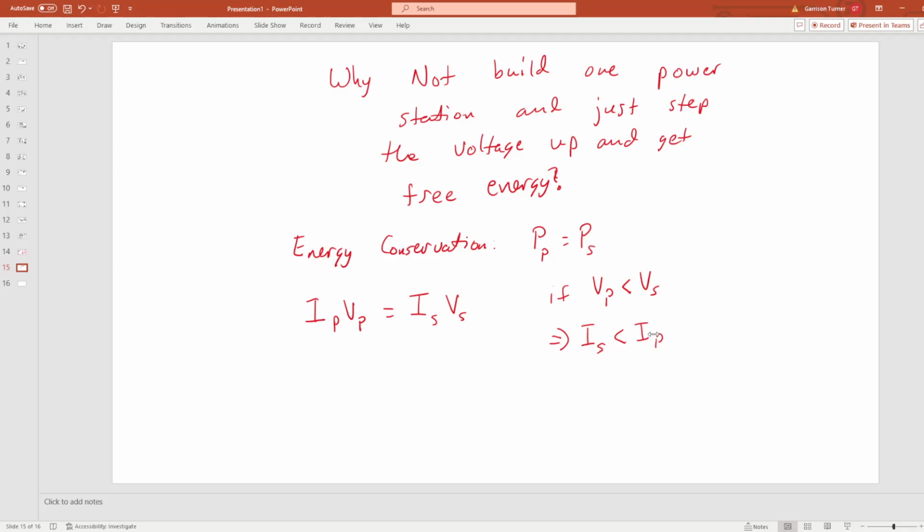even a 1.5 volt battery, right? If energy conservation weren't a thing here, then in principle you could step up a 1.5 volt battery and just keep stepping it up and just keep drawing power from it. But that doesn't make any sense. And if you think about it, it shouldn't make any sense because let's say you take a AA battery and you just keep stepping it up, stepping it up. That battery is going to have to supply more and more current. But what do batteries do? They use their charge and then they die, right? They're no longer usable unless they're recharged.